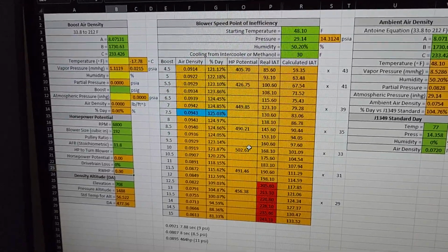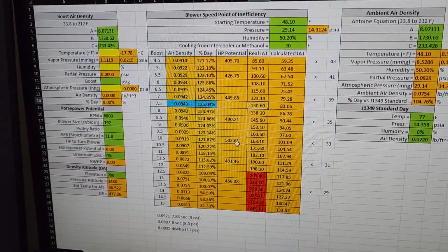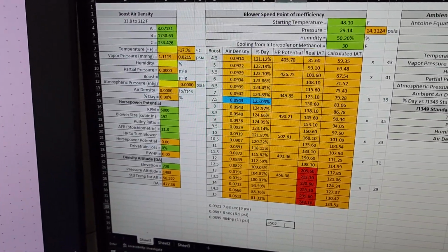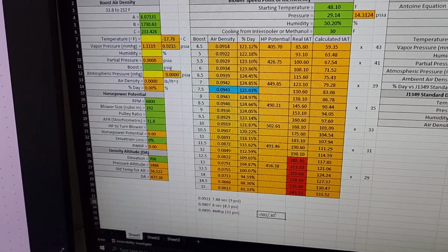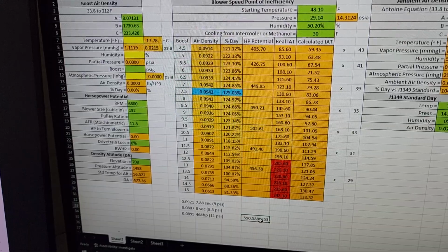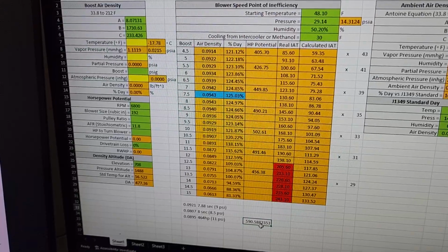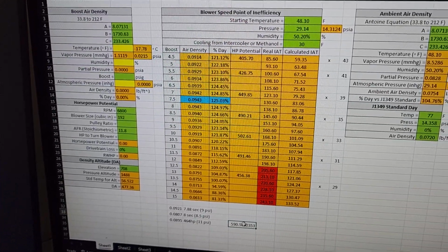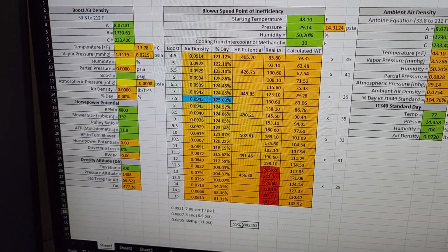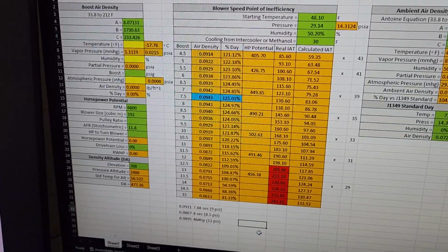And actually these numbers aren't going off of that, so I would have to, actually I don't even have to do that. So 502 divided by 85%, that'd be 590. So it's telling me this 502 would be 590 wheel horsepower. And these 700 R4s are usually about 65 horsepower, but on a four-wheel drive, they can be up to 120 horsepower. So this is a pretty accurate amount of powertrain loss. That's between 65 and 120. So like I said, it's usually pretty close.